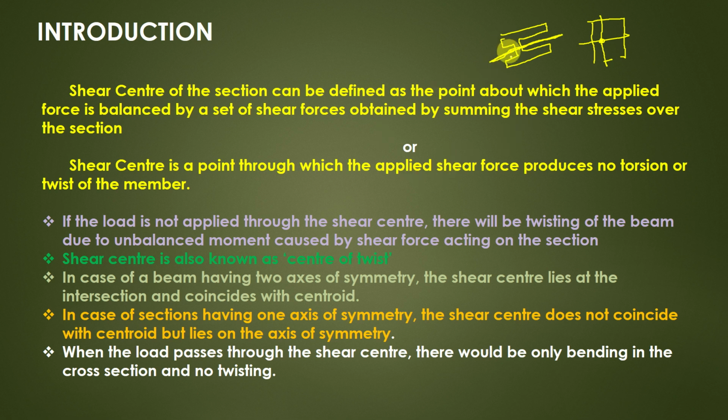And why we are finding the shear center is, this is not a practical point, this is an imaginary point that describes the location of the load. If you could apply load at this point, there will be only bending, there will be no unsymmetrical bending then. So it will be bending, there will be no torsion or twisting.